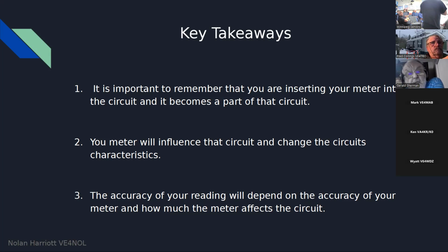And that alone is one of the key things that will affect the accuracy of your readings, right? As well as displays and the quality of the meters. So just remember that when you use your meter to take the measurement, you are in fact changing the circuit just by measuring it.